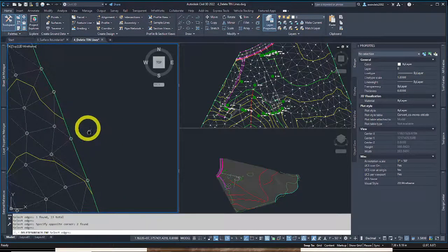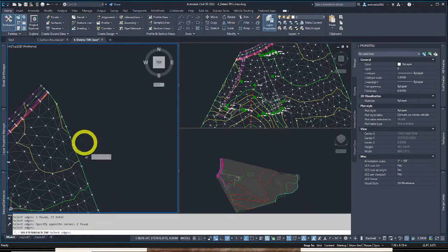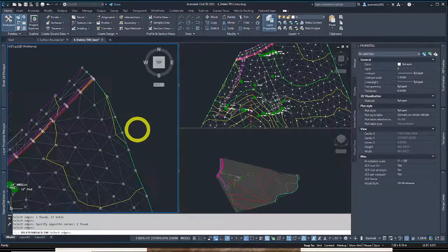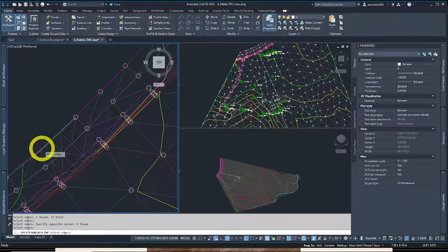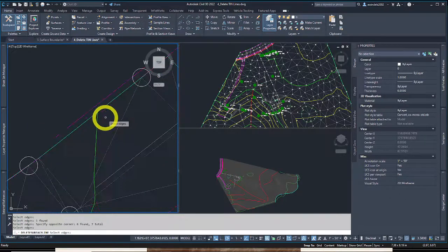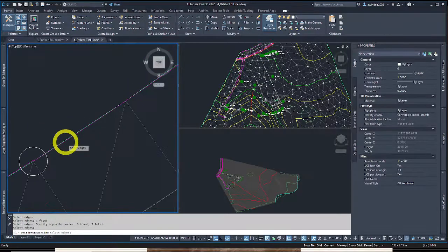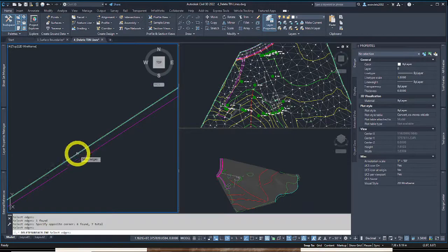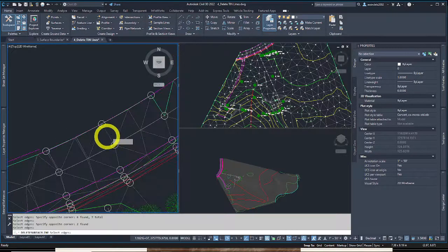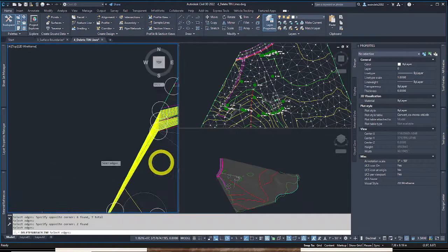On a big, large LiDAR surface, I might actually draft a polyline around it first because of the unwieldy nature of retriangulating surfaces, and then I'll tell that polyline to keep the surface boundary at the outer boundary. But these GPS shot surfaces, traditional surveys, I mostly just delete out the triangles along the periphery. That is the preferred method, industry method most of the time.